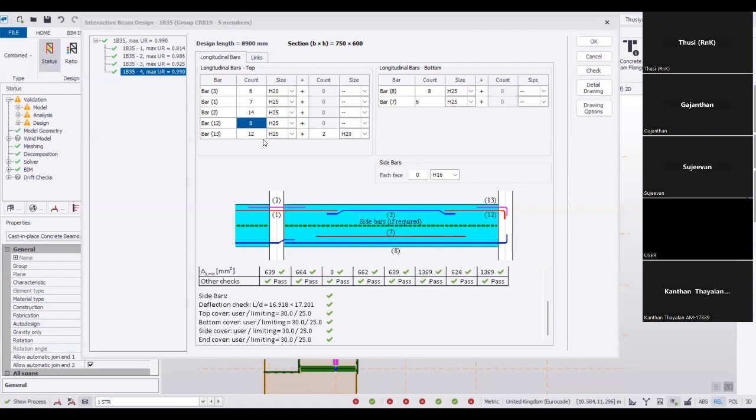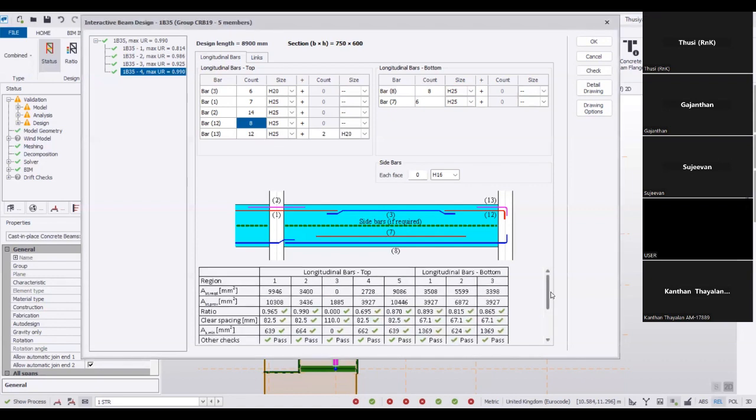So I'm going to leave it because all the designs are satisfied, right? So even though rebar is heavy, I leave it, right? So now it's workable. So I leave it first. This rebar also quite close. So I changed this one to 25.